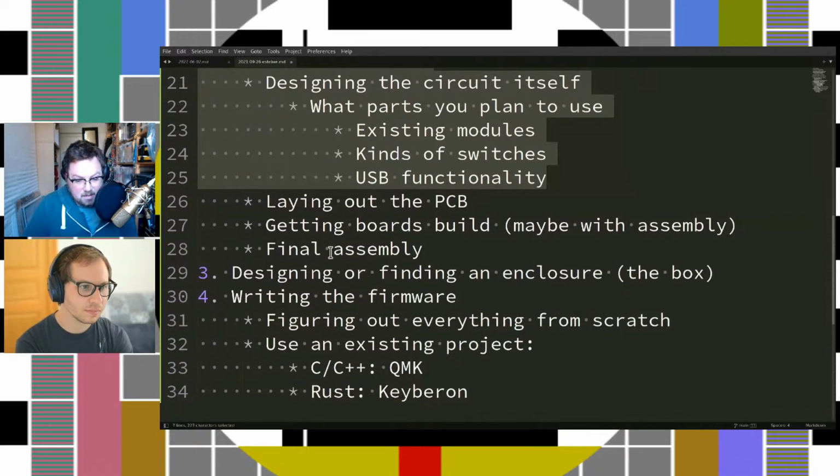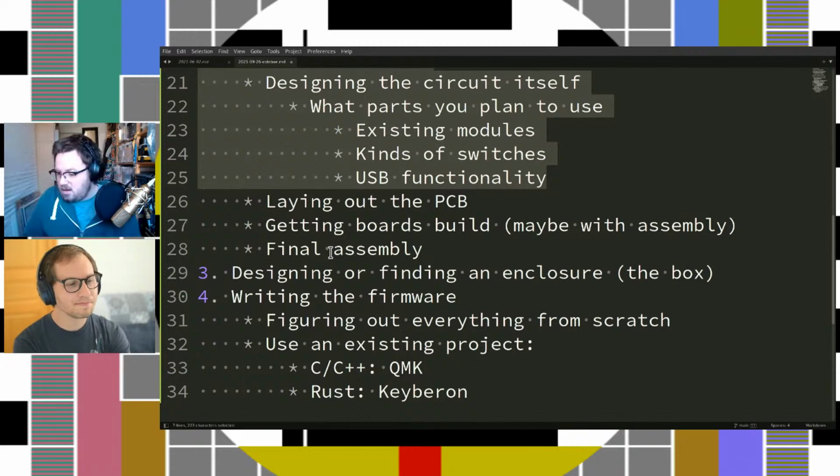480 megabit per second gets harder, where you need to start controlling that you've got a pair that needs to be the same length on the circuit board, and certain things are controlled and you don't design things wrong. And then I'll admit USB 3 just becomes way harder, because it's that times 4. You've got multiple channels and they all have to be controlled, and you often need special controlling ICs. It's not impossible. I'd be comfortable with the 12 megabit part if I was feeling brave on a certain day. Now, after having worked for about a year, I might try and tackle 480 megabit, but not be certain that it would work the first, second, or third time, and I'd probably just avoid USB 3 at this point.